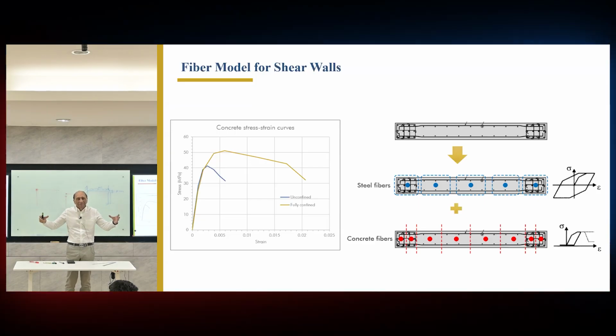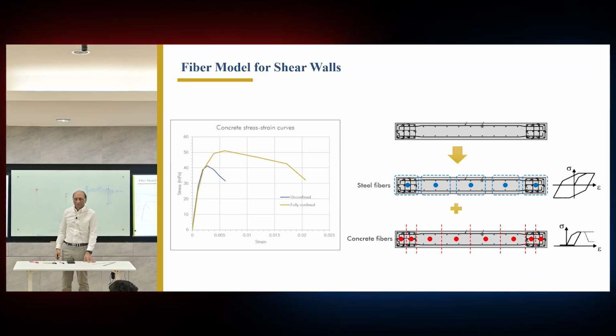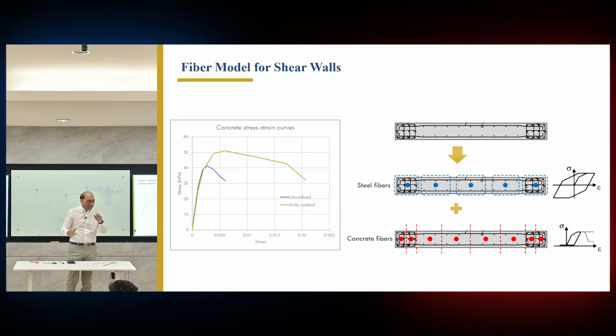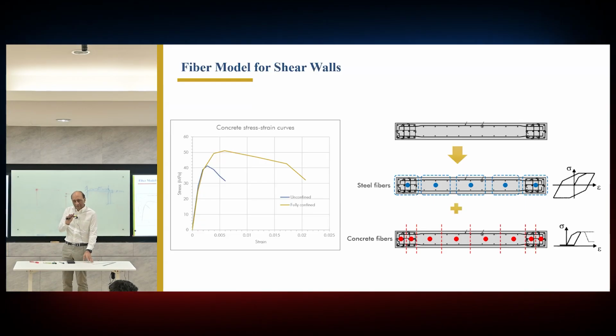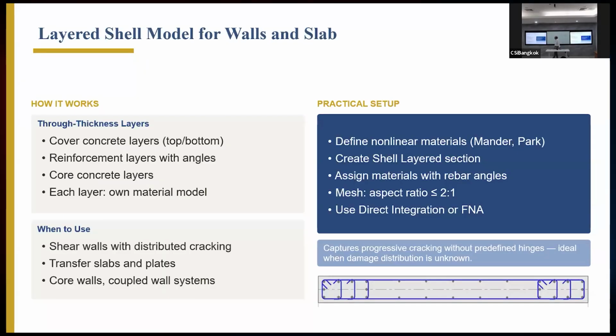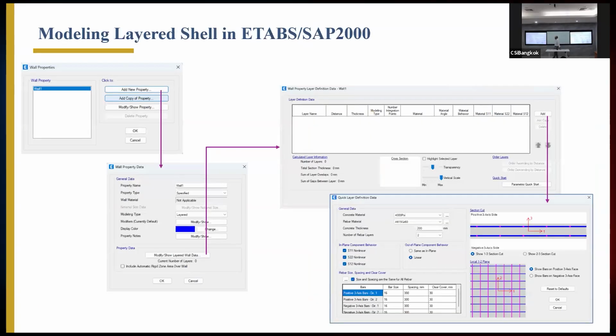So they are not brought back into a single cross section with one line. The wall geometry is still maintained. So the wall is actually divided vertically into these line elements that deform together with shear fixed. So that's the fiber section. And then finally, the layered shell. So layered shell is the most complex modeling that you can do at the moment in SAP, or any other tool.